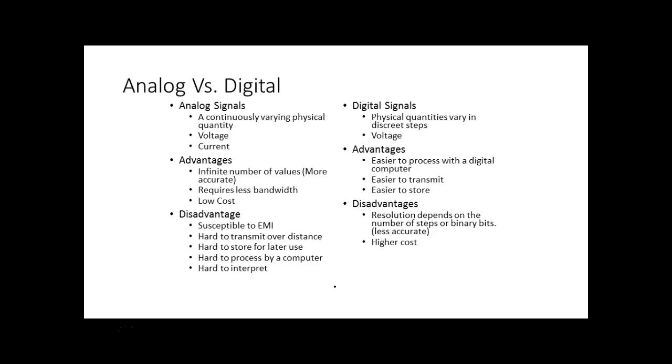Right now, if I'm using a single bit, then I have very poor resolution, because it's only going to recognize one voltage. When it exceeds that voltage, it's going to recognize it. When it doesn't exceed it, then it's not going to recognize it. It's not going to be true. But if I'm trying to figure out what temperature it is, I cannot use on and off. I've got to have a weighted binary number that indicates the temperature. I've got to have a transfer function.